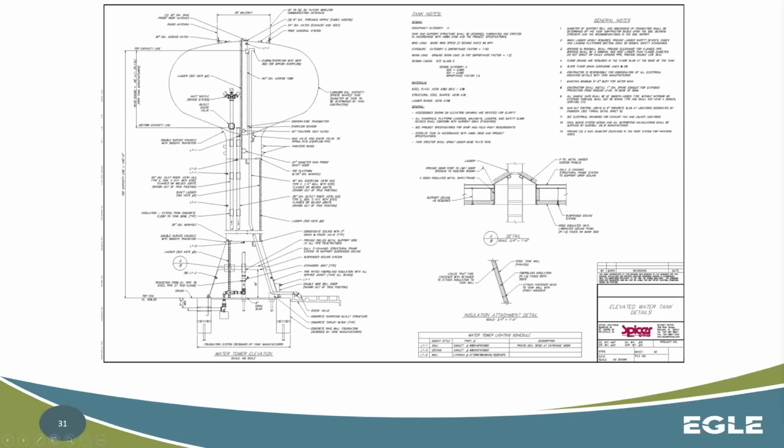So you're getting water coming up and out, spraying in multiple directions, and then you're having water leave the tank out a different pipe. Okay, so coming out at the top and then leaving out the bottom. So it's probably going to get some pretty adequate mixing because of that. Though maybe it's not the norm, and maybe it costs a little bit more, it might be beneficial, especially if you're dealing with long periods of stagnation for that water, which are leading to DBPs and other things.